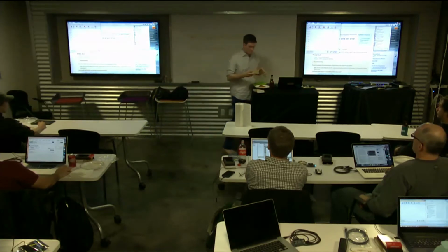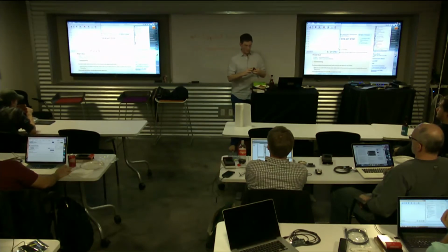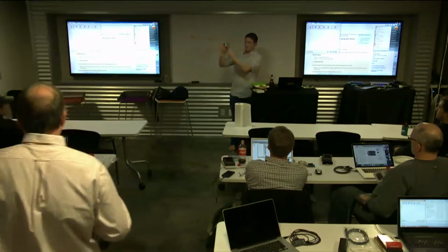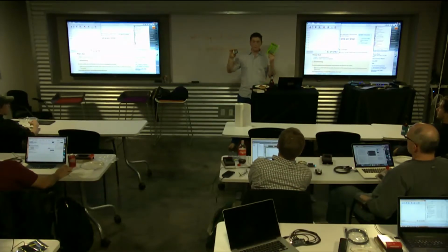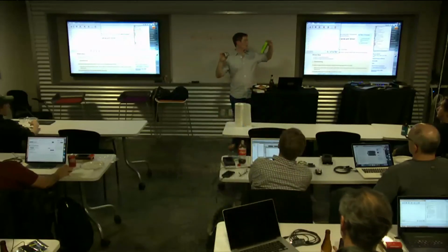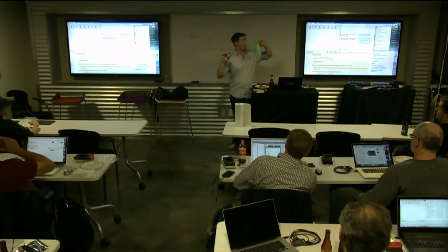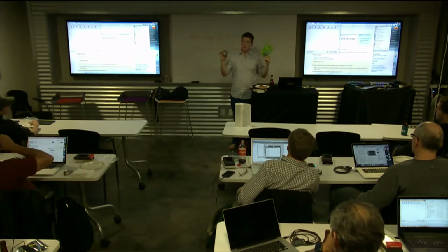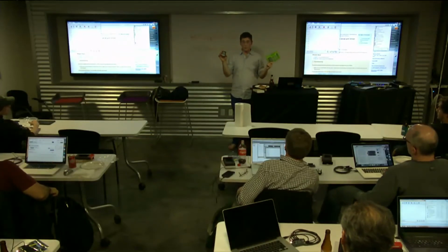So, this is from a third-party company called Seed. They make this really, really cool thing called Seed Grove, where they have this Arduino header compatible shield. It has all these connectors, some of which are I2C, some of which are analog, some of which are digital. And they sell these huge boxes of sensors. In this, I've got a relay, a fire sensor, a button, vibration sensor, a potentiometer, a touch sensor, a LCD, and a couple other things. And they all have this form factor. You can plug them in, and you've got sensors, and they work.